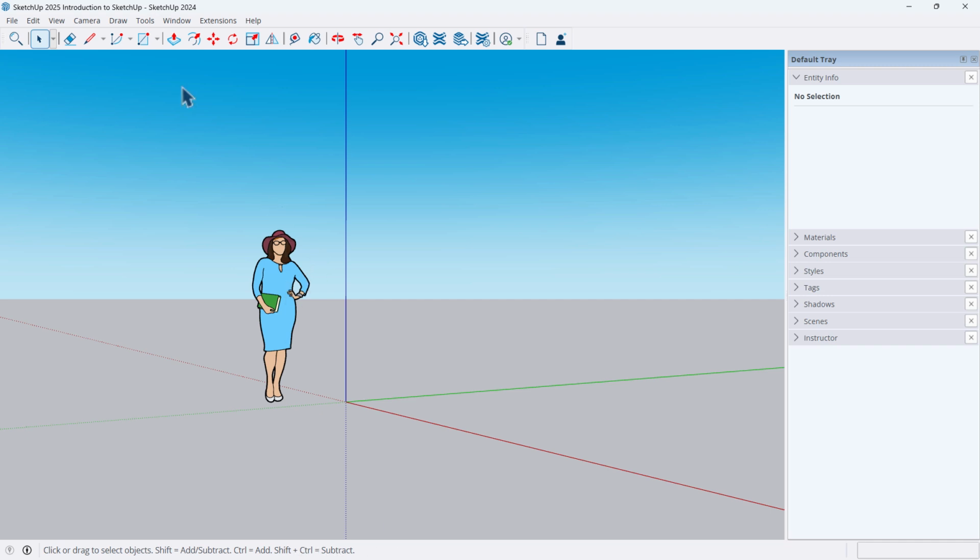So essentially it means, and we'll go more into this in more detail as we start to model, but if you're on your move tool, and again, a shortcut could be if you type M, so let me deselect. I hit spacebar to get back to my mouse. If you hit M brings up move, right? We talked about this is our move icon.